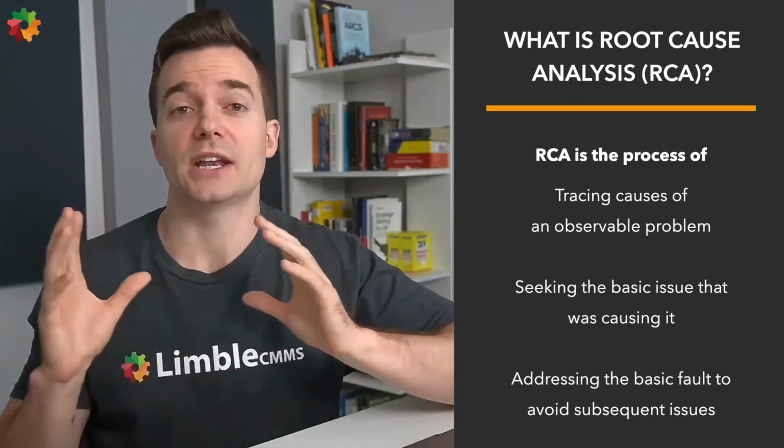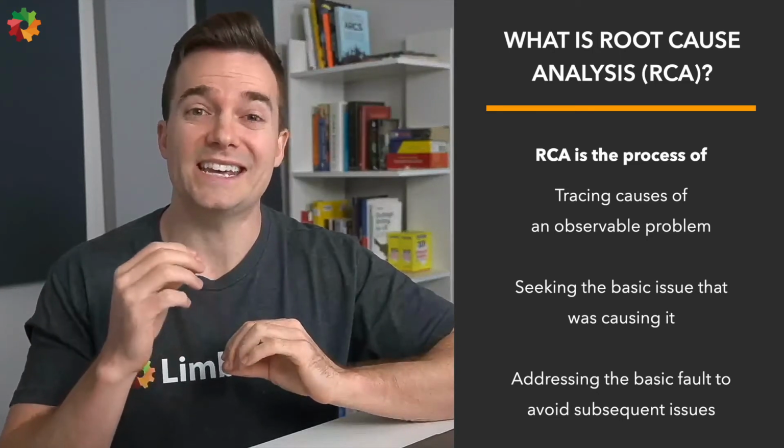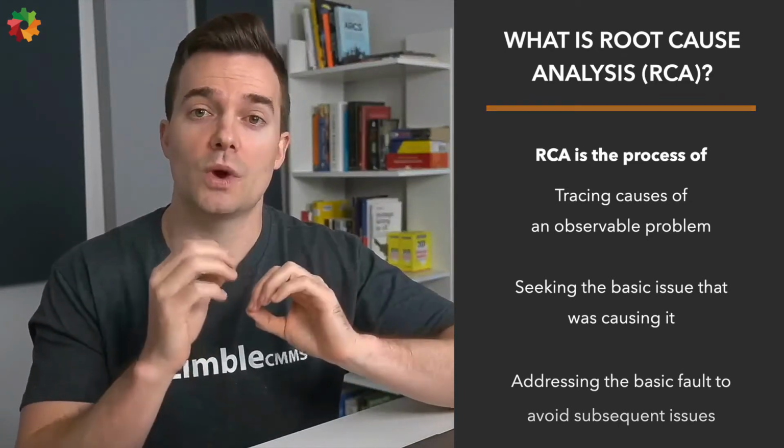But if the team investigated further, they would have realized that what caused the bearing to fail was an issue with the lubrication system. Addressing the lubrication system instead of simply replacing the bearing would have kept the machine working for much longer. So root cause analysis tries to follow the chain of cause and effects to pinpoint the problem that, when eliminated, makes all the other faults disappear.